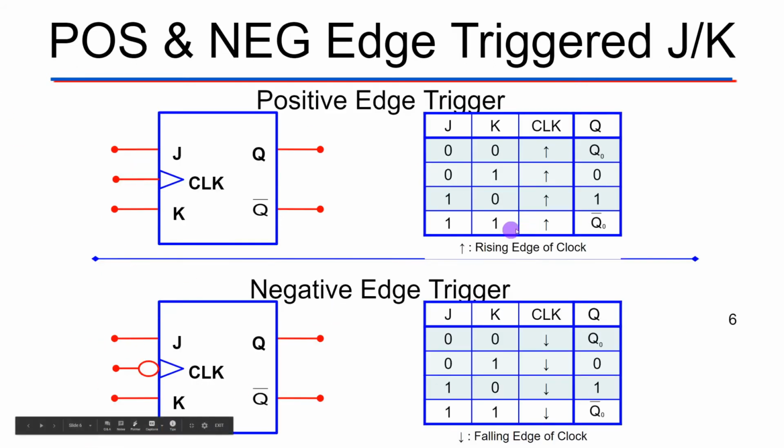This is just to show you the distinction between a positive edge trigger and negative edge trigger. Again, it's usually called rising edge or falling edge. And notice these are the exact same outputs. The only difference is that the values we're saving are only written on the falling edge of the clock, when the clock signal goes from high to low, or from 1 to 0.